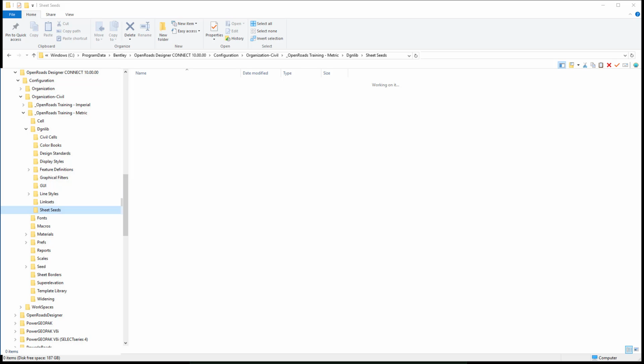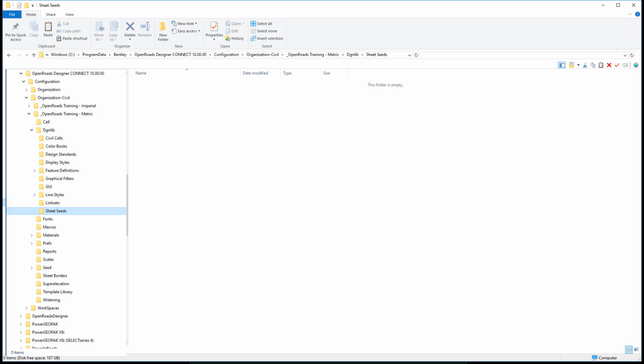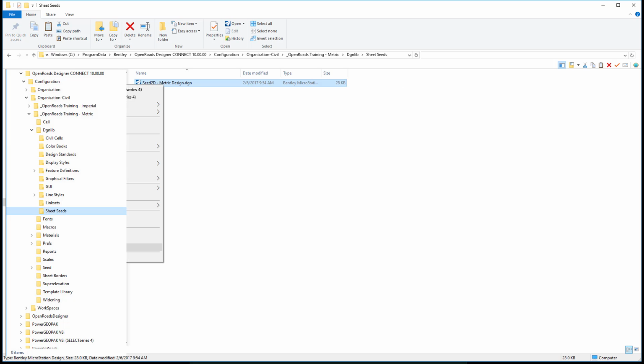So to do this, we're going to go to our seed folder, and again, I'm going to grab our base C2D metric file. I'm going to make a copy of that, and I have a new folder under my DGN lib folder structure called Sheet Seeds, which is where we're going to be working for the remainder of this video series. I'm going to paste that file in here, and then I'm going to rename it.